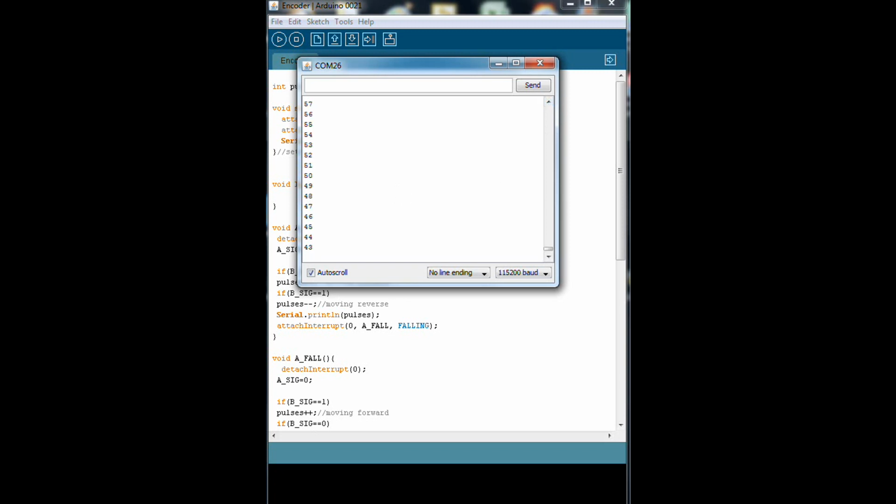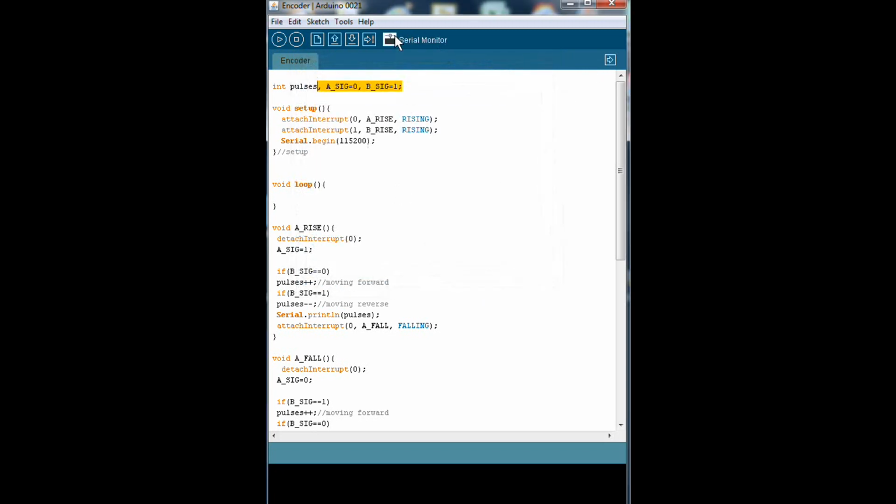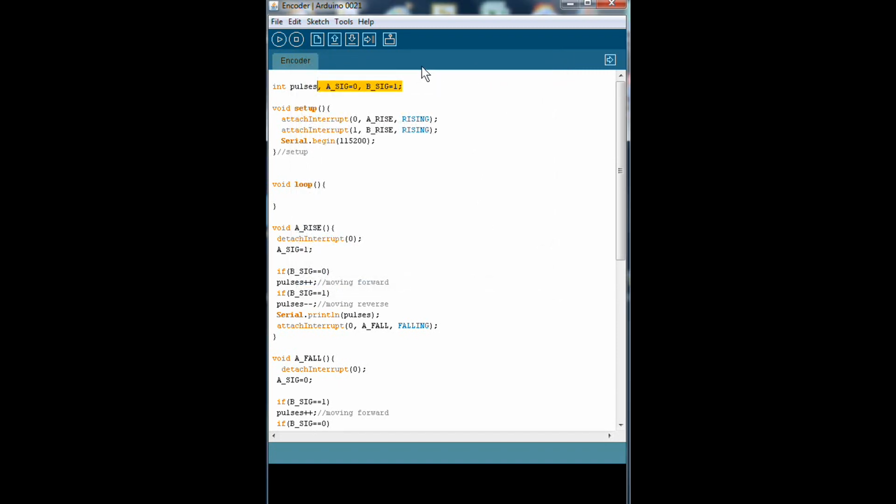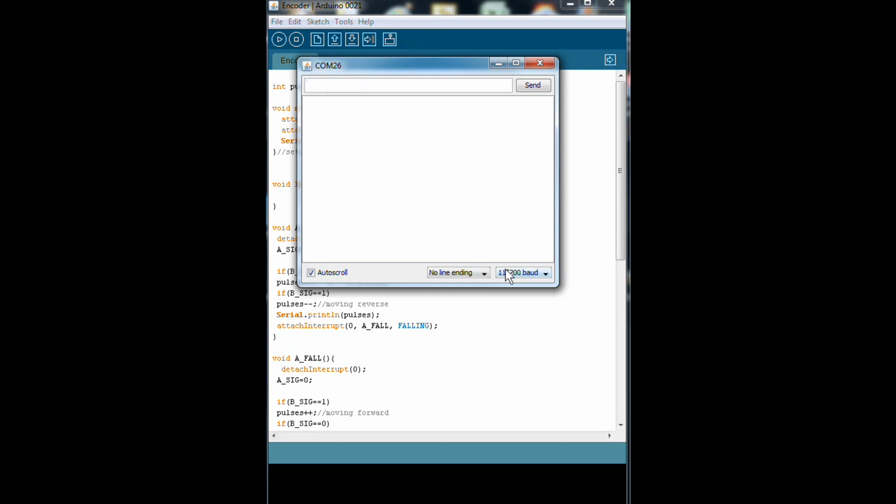I wasn't really going to go into the processing code, but one more thing about incremental encoders. It always starts at 0. So you're not getting your absolute position of the wheel, because on power down, I could be spinning this 100 times and it's power down. As soon as you power up, there's no way to know where the wheel is right now. So it's all incremental from where you last were, and that's how it figures it out. Okay.